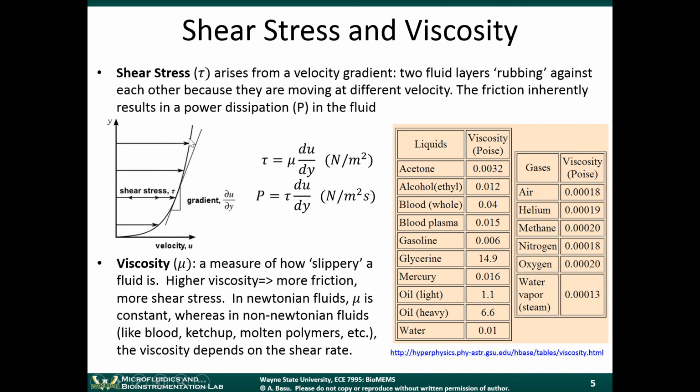So this creates a velocity gradient. We talked a little bit about this in the first lecture. This gradient is given by du/dy. u is the velocity, and y is this y coordinate. So the slope of this line is the velocity gradient. What a velocity gradient means is that the fluid here, for example, is moving faster than the fluid here. So if you imagine flow in a pipe, and we imagine a block of fluid, let me just draw this.